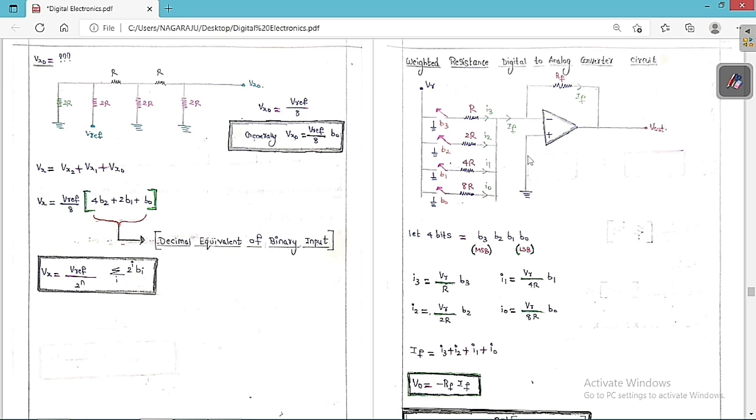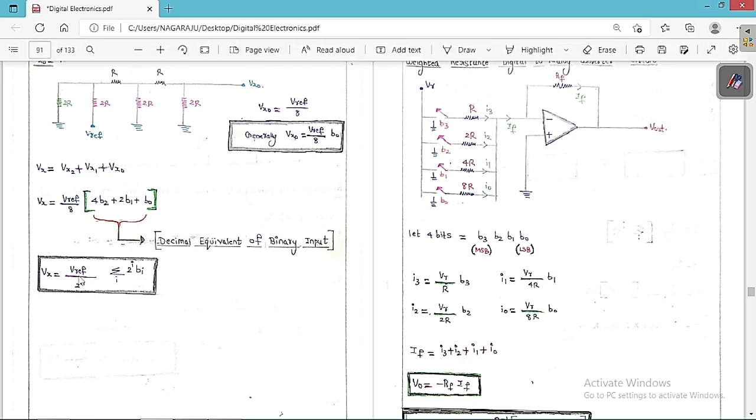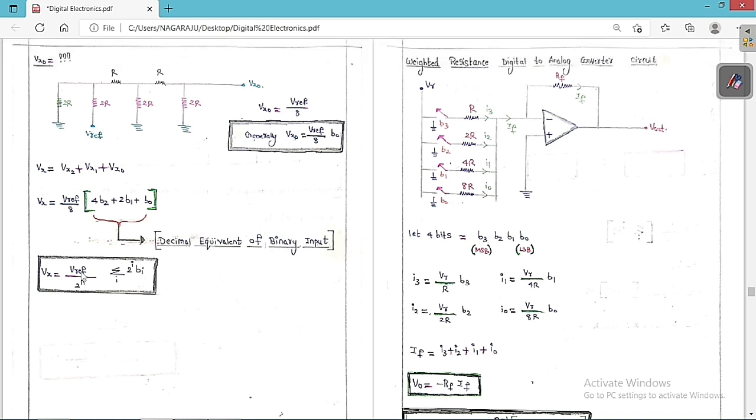So this is a circuit that you always have to keep in your mind. See, I have already told you one important point, I think you have remembered, in the DAC. When I told you about the formulas, I told you the resolution in case of the R2R type of DAC is V reference by 2 to the power of n. This is the formula of the resolution for the R2R ladder type DAC, VR by 2 to the power of n. Yes, this is the value you are seeing right now in front of you. This is the formula which is the proof of this one. So we can say for the R2R ladder type of DAC, the resolution is equal to V reference by 2 to the power of n.